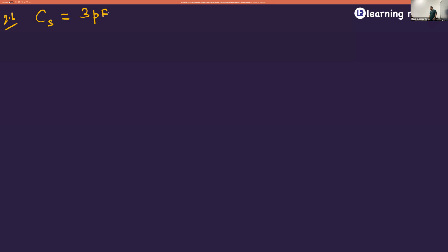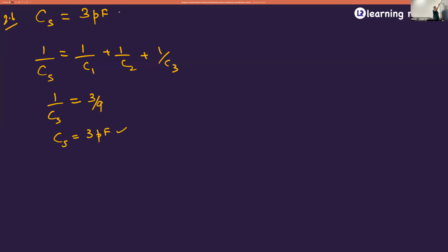Because you'll write 1 by CS is equal to, see, going forward, I'll use S for series and P for parallel. So 1 by CS is equal to 1 by C1 plus 1 by C2 plus 1 by C3. Everything is 9. So you will get the answer as 3 by 9, but you should not leave it like that. You should take the reciprocal. So that will be 3 picofarad. That's what I wrote directly.